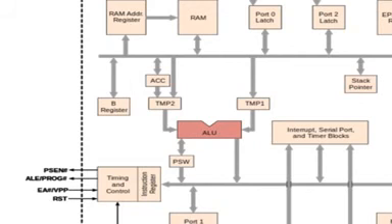In the case of multiplication, A will have the lower byte of the result and the higher byte will be stored in the B register.